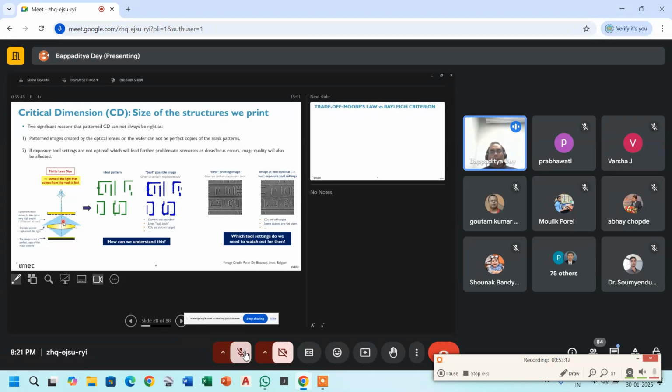That is basically, as I said, because your lens cannot capture all the higher order diffracted patterns. It can only capture the zeroth and first order at maximum. All the other patterns are lost. Based on that, the engineers and the tool vendors on the hardware part work hard, so you can see how critical it is to even keep this spec within the tolerance limit.